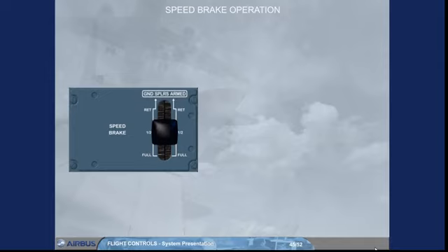If an autopilot is engaged and the speed brake lever is moved fully back, the maximum surface deflection is limited to the deflection relative to the half position. When flying at high speed, the speed brake retraction rate is reduced. So, retraction may take around 25 seconds.